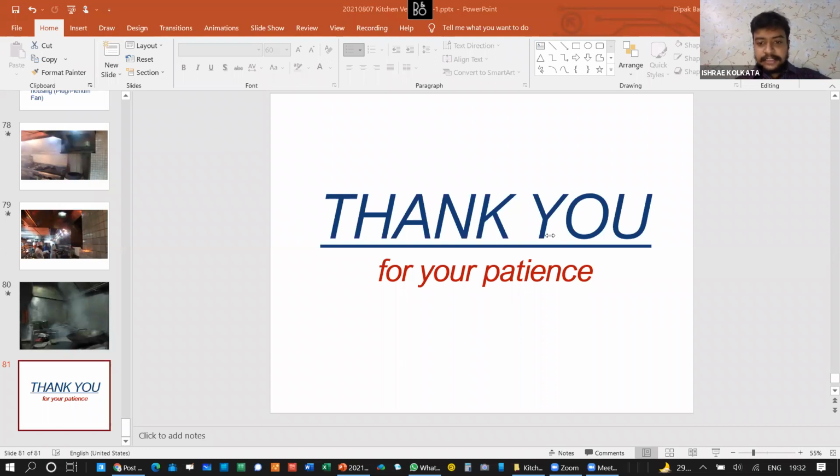What is the minimum gauge of GI ducts for kitchen vent exhaust? The answer is 16 gauge. SS is 18 gauge, right? So for GI it will be 16 gauge.